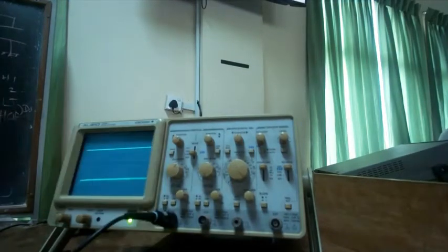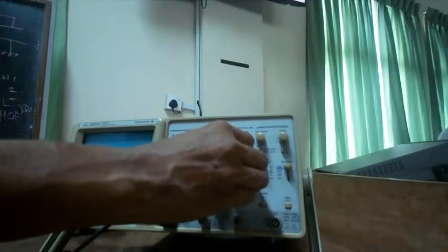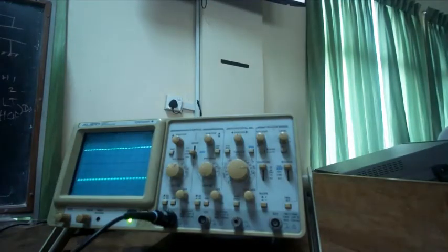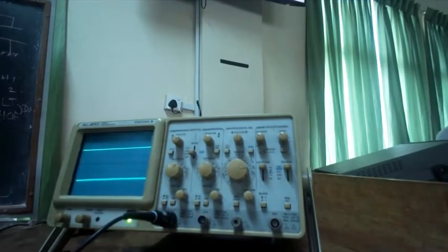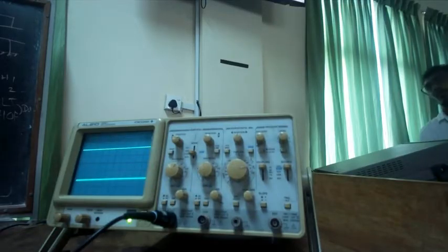But if you put it to chop mode, you will see these choppy waveforms. Okay? If you remove it, you won't see these chopping lines, right? So that's all-time chop mode. Therefore, this is the dual mode. So you have channel 1, channel 2, dual, and also in some ones you have an add function.